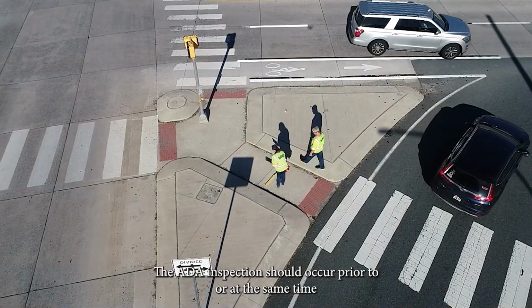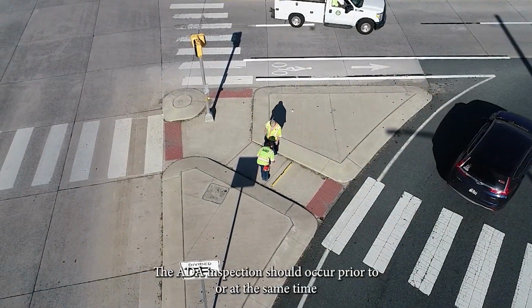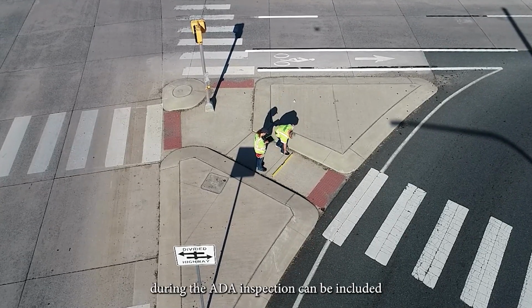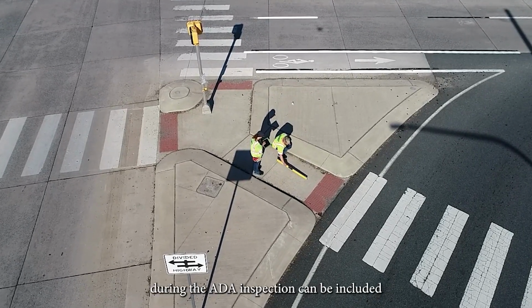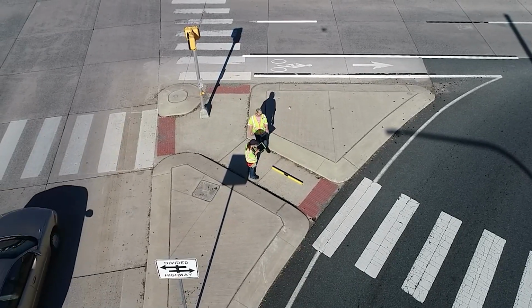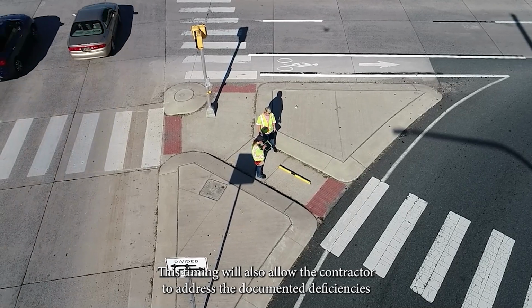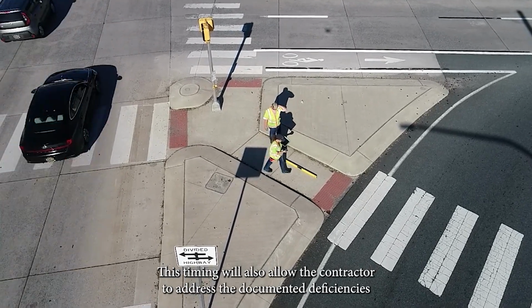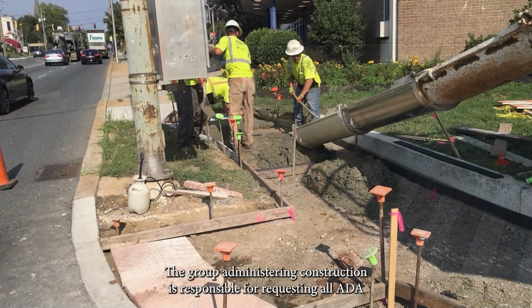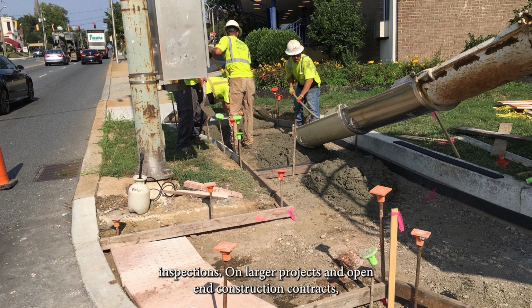The ADA inspection should occur prior to or at the same time as the initial inspection, so that the items identified during the ADA inspection can be included with the punch list that is generated from the initial inspection. This timing will also allow the contractor to address the documented deficiencies prior to demobilization from the site. The group administering construction is responsible for requesting all ADA inspections.